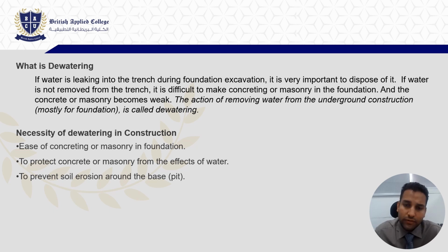So dewatering is a really important criterion which you need to see. You do dewatering in places where your water table is really high, that means when you dig for foundation you will find water there. In those places you need to do dewatering. Also in places close to the sea, rivers, or something like that, you need to do dewatering before starting your foundation work.